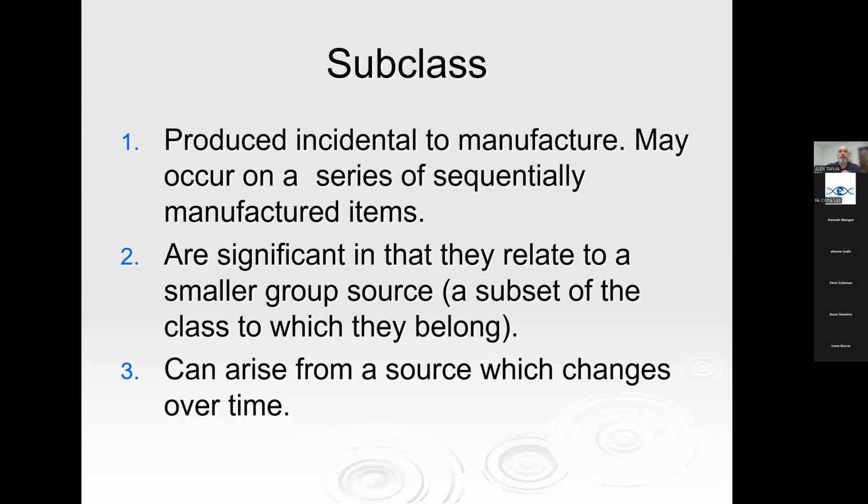So let's say hypothetically you're making a firing pin. This firing pin has a rounded tip. And so the way it's manufactured is it is turned and a knife blade comes in contact with it. So as it's being cut, chips will form that might cut the actual blade. And so if you look on the surface, this is what the firing pin will look like. And you can look at this and go, wow, there's a lot of marks here that you could use. All of these wonderful lines.